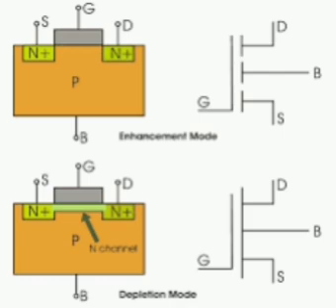Photocurrent flows from N to P. Photocurrent is a minority carrier current. It does not provide gain. Photocurrent is a diffusion current. It is used in remote control sensors, in the design of optocouplers, and to read the audio track recorded on motion picture film. When a photodiode is forward biased, it behaves as a normal diode, and the effect of light on current is zero. Avalanche photodiode, APD.